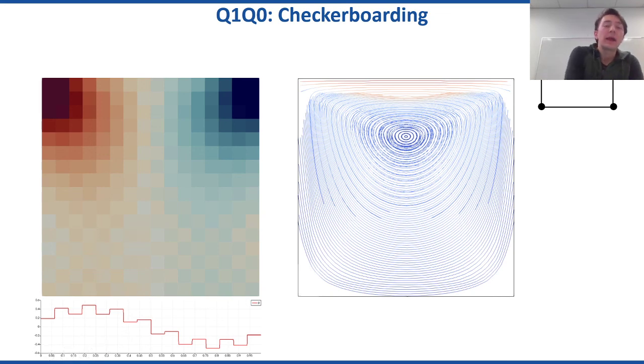And I'm not entirely sure why we do obtain a solution at all. I suspect that it is due to numerical roundoff that the solver is still able to find a solution. But this is also showing that this spoiling with the checkerboard pattern could have been of any magnitude. You can get very large jumps from one element to another, or small jumps. You might not be able to recognize the original solution at all.